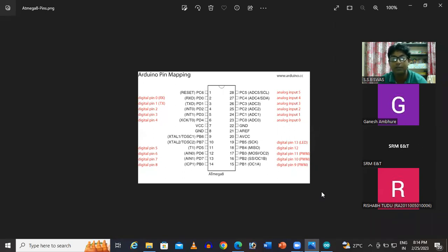So basically a microcontroller can be used for several control purposes, but I have focused only on working with power electronics and control. If you know these things, meaning general purpose digital IO handling, ADC, interrupt, timer and PWM, then I hope you will be able to implement most power electronics equipment. If you can use your academic concepts with this, you will be able to do that.